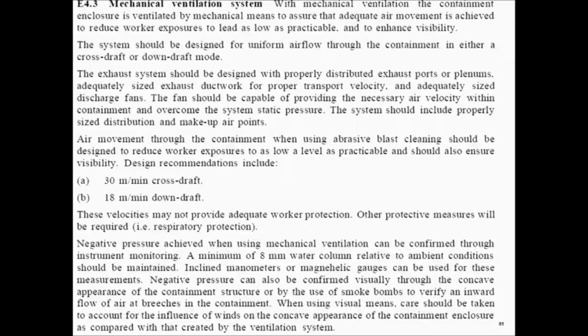Under the Australian Standard 4361.1, as detailed, we have the responsibility to minimise the amount of exposure by creating mechanical ventilation. It's all about exposure to lead, which enters our blood system if we were in there, through the skin and our respiratory systems. The volumes of air create flow greater than static pressure, thus reducing the exposure to personnel.